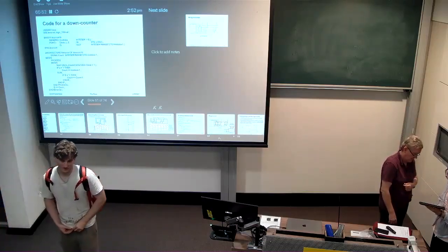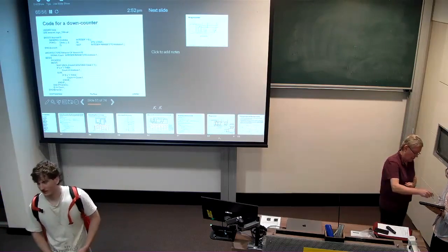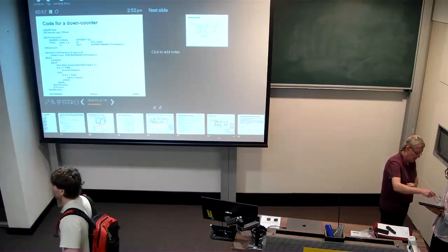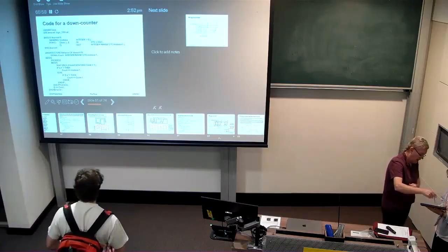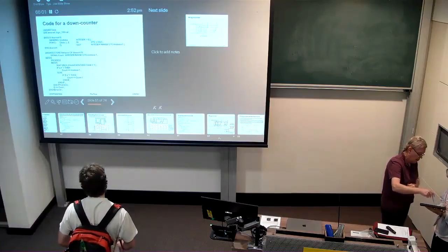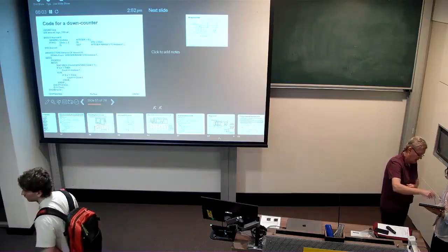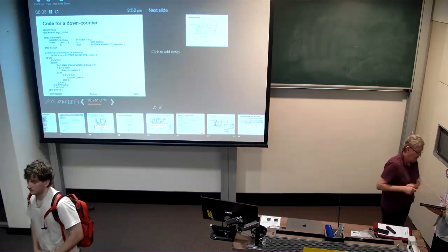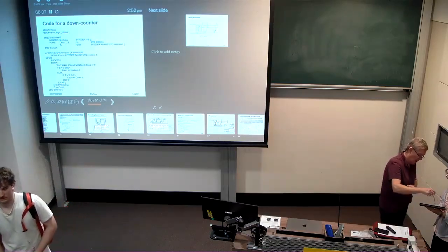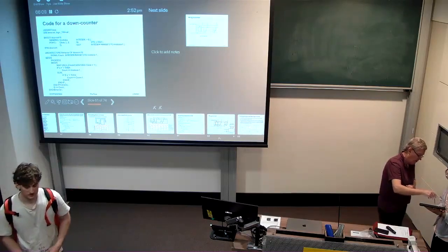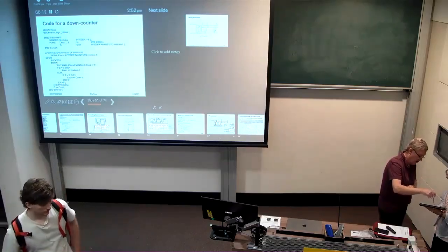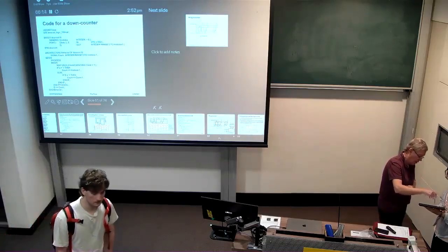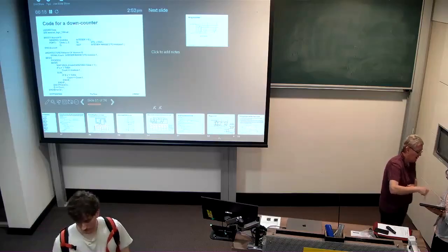Okay. But we have to wait for this gate to change. And ideally, we have to wait also for the delay on this gate before we change D, because we want that 0 here to impact P4. We want the 0 here to become a 1 out here before we change D.